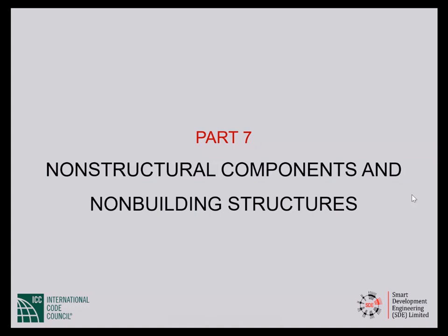I would say keep the gravity in place. Dead plus live would be fine. Dead plus a little bit less than the full live load would be fine. But to look into load combinations is not something that is called for.